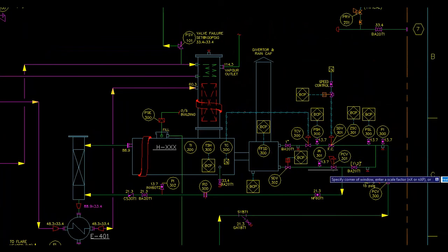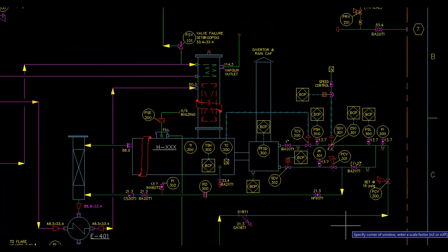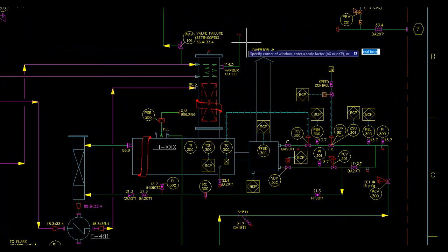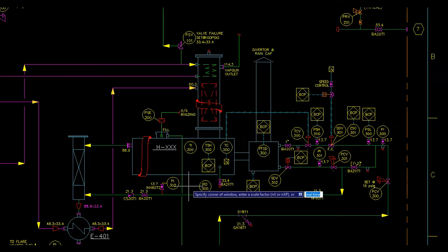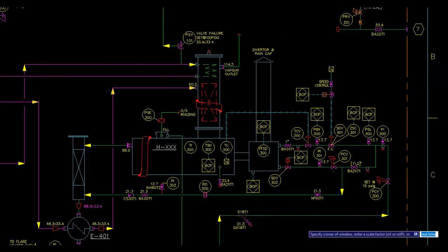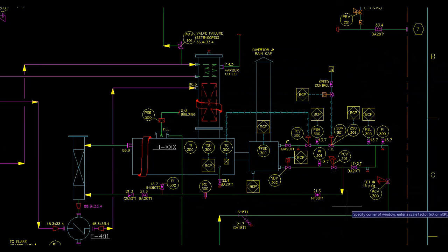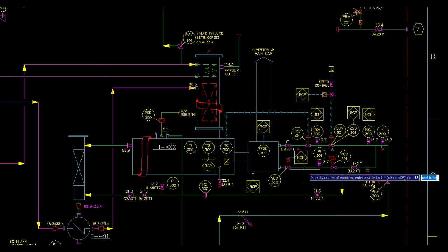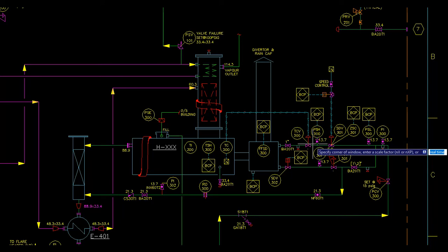While we are at the reboiler, all the arrangement you see here is standard in Canada. It goes by a code called CSA B149.3. This incorporates all the necessary safety to be included in the fuel gas train. Typically, all line heaters and reboilers will follow this code.